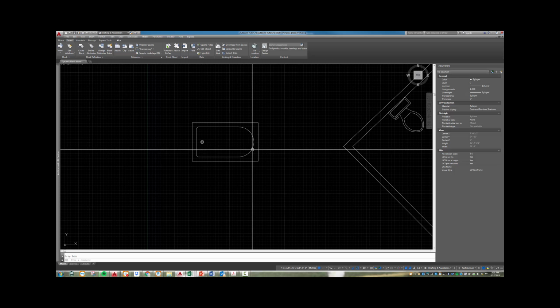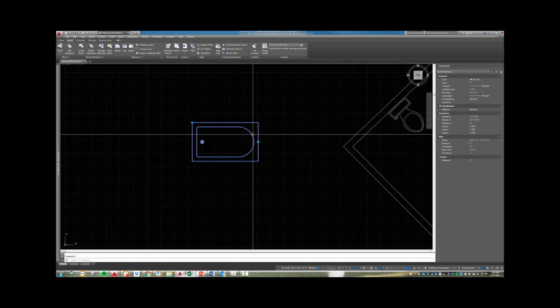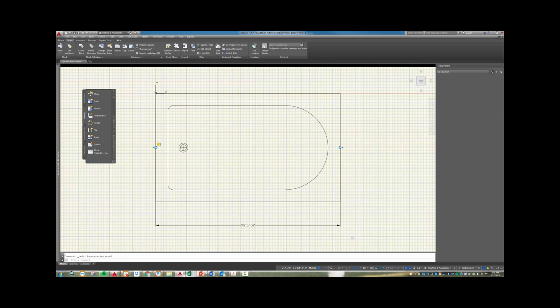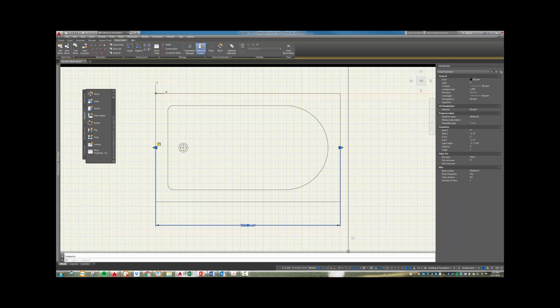Now one thing is, you can't get a tub that's 6 foot 3 3/4 inches long. So you want to put some limits on how far you can stretch it. So I'm going to double click on it, go back into block editor. And I have my properties toolbar open, Control 1. So if I click on this distance one, over here in my toolbar, underneath this value set, right now the distance is set to none. So I'm going to pick list. I could do increment, 1 foot increment say, but instead I'm just going to do a list. And the list value currently is 5 feet.